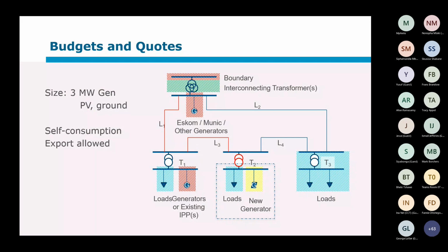Okay, so for PV, one can work with a rule of thumb of about 1.7 hectares per megawatt. That's not ground mounted, eh? Well, that would be roof mounted as well, if it's elevated compared to installed parallel or flat.